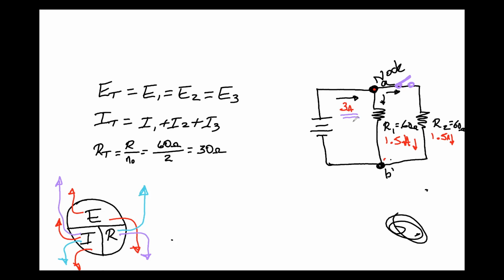In order to be consistent with Ohm's law, if my current is increasing and my voltage has remained the same, because we haven't changed that voltage, that means the total resistance of the circuit has to be going down. That's the only way we can increase the total current in a circuit without increasing voltage, because they are inversely proportional. Okay, so let's get moving.